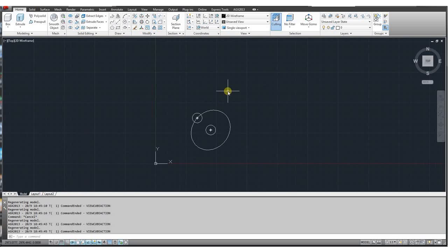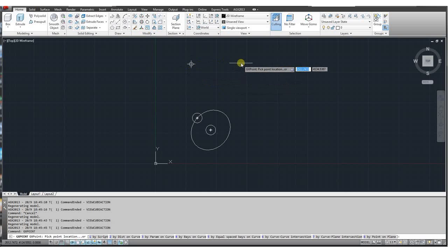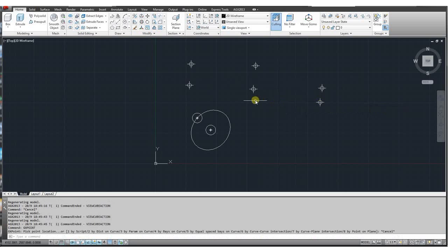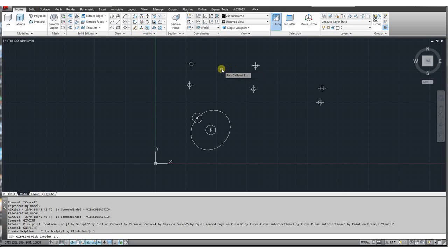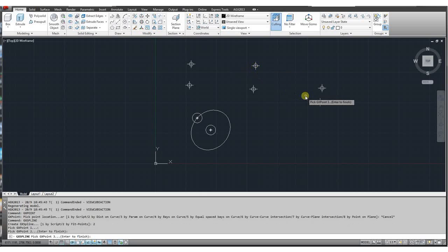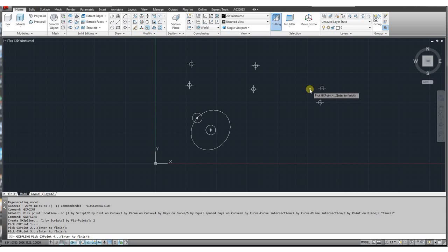Right, now to create a spline, we need points. So if I type in GxPoint, I'll just create a spline out of 3 points, and another spline just below that out of 3 points. If you type in GxSpline, create by fit points. It only has fit points at the moment. You get prompted to select your first GX point, and your second GX point, and third point, and so on, and enter when you are finished.